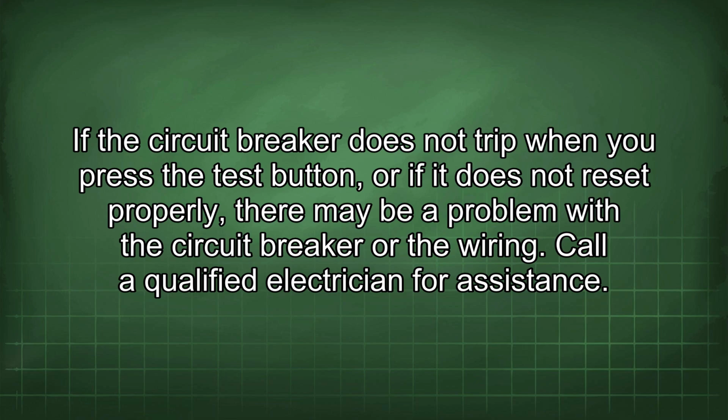If the circuit breaker does not trip when you press the test button, or if it does not reset properly, there may be a problem with the circuit breaker or the wiring. Call a qualified electrician for assistance.